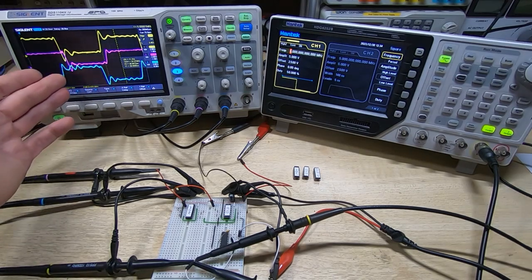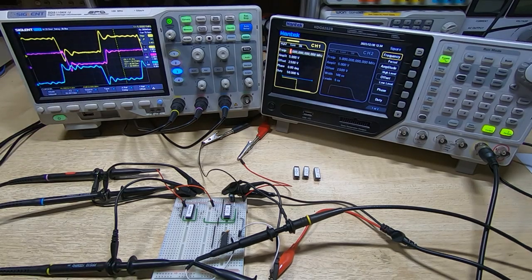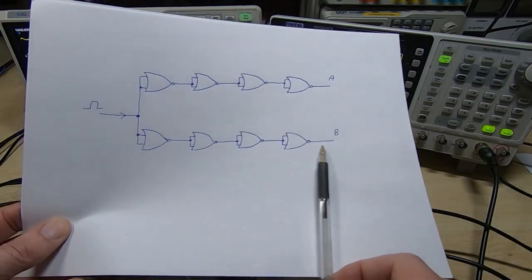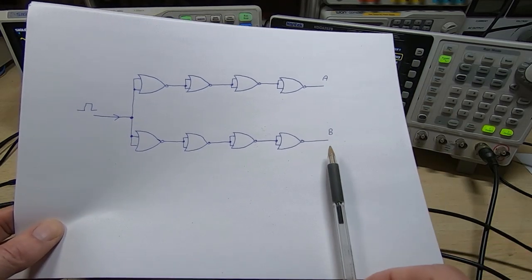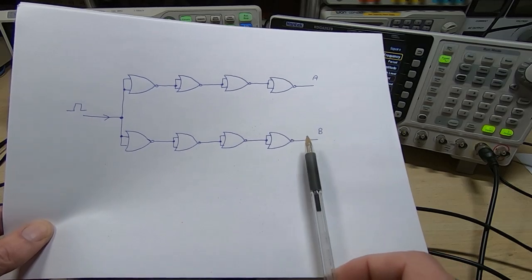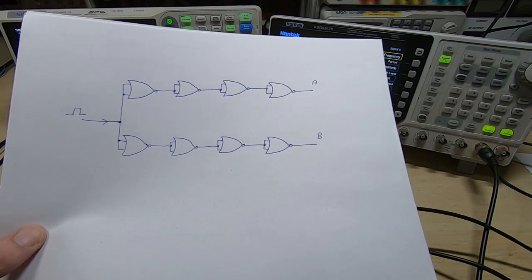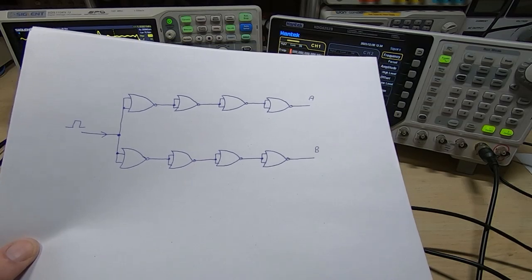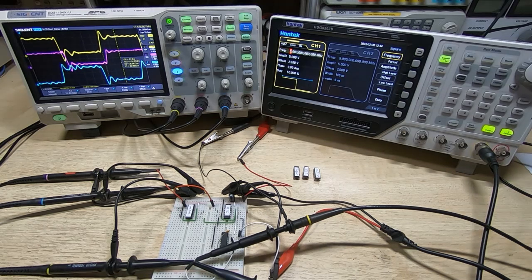So hopefully this demonstrates the effect that we're having and clarifies the point I'm trying to get across here, which is that the output from a given string of gates in the system, in a vintage system, must occur within a particular time window. If it fails to do that, then other events that are occurring on the board are going to effectively clash with it, and the overall system is going to stop working. So what you're looking for when you're probing around the board is something like this.